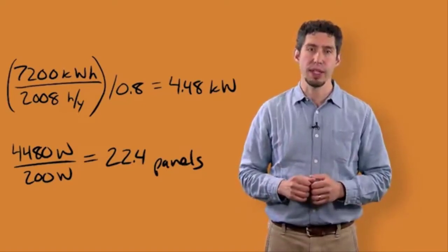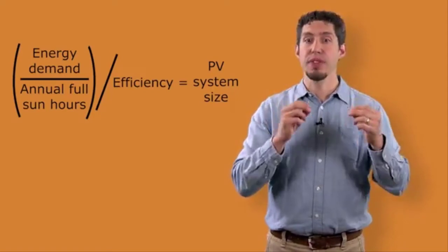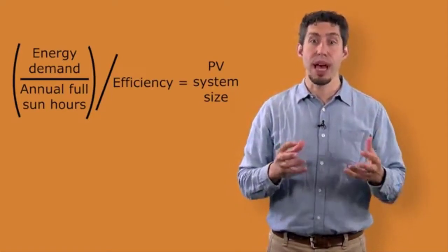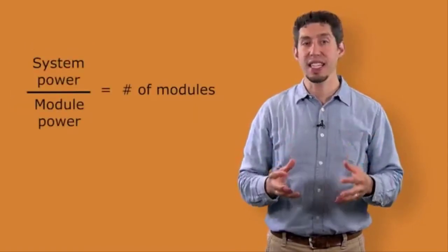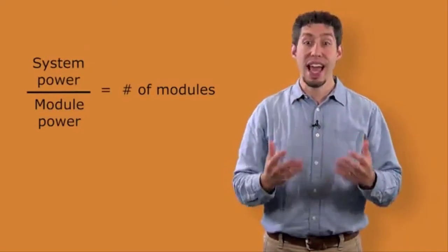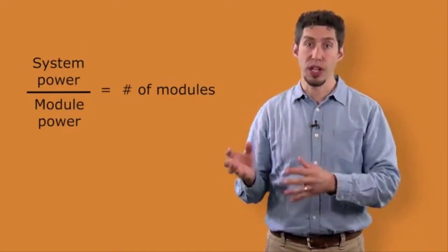So in review, we start by looking at the total electrical energy load. Then we look at the sunlight level for the location we're in. We then divide the total electrical load by the sunlight hours and the system efficiency. That will give the size of the photovoltaic system power. We then take the size of that photovoltaic system and divide by the power of the individual module, and that gives us the number of total modules required to support that original electrical load.